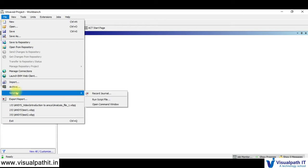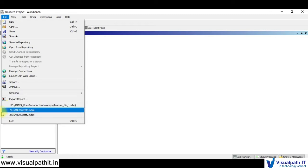Then there is scripting. Scripting will help us to record some operations that are performed in the project schematic, and we will be able to rerun them by running the script file again. Record journal will record the operations that we are performing on the project schematic window, and by running the script we will be able to rerun the recorded journal. Then there is a list of files that were previously opened, and the exit button closes the Workbench window.